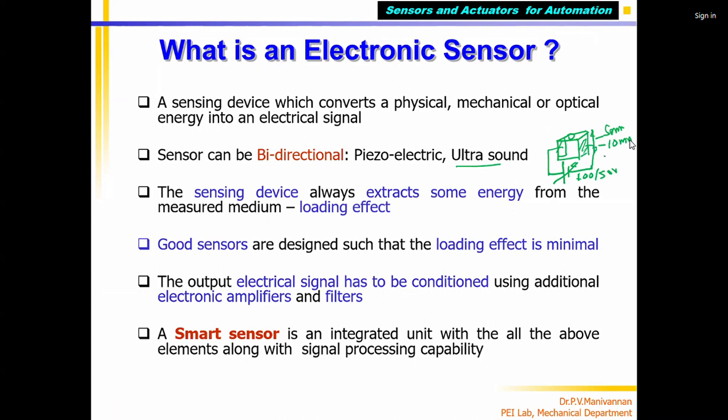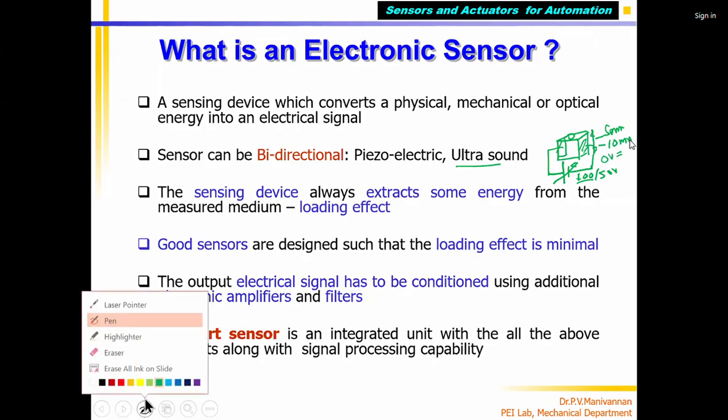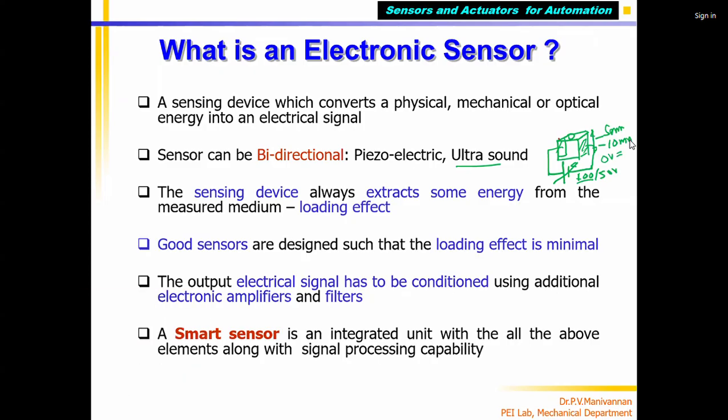Now when I apply 0 volts, 10 mm was the height. Now I apply, for example, 100 volts. Then the height will increase. The crystal deforms and physically becomes bigger, now for example 11 mm. In the vertical direction it becomes bigger, so we call it a strain. A strain is produced, it deforms. Now, if I remove the voltage, it comes back to 10 mm.